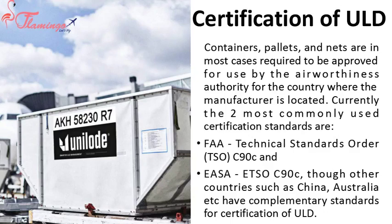Containers, pallets, and nets are in most cases required to be approved for use by the Airworthiness Authority for the country where the manufacturer is located. Currently the 2 most commonly used certification standards are FAR Technical Standards Order C90C, and ISO C90C, though other countries such as China, Australia, etc. have complementary standards for certification of ULD.